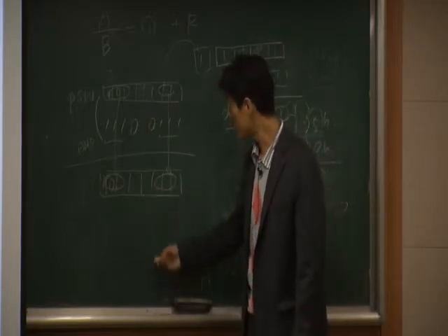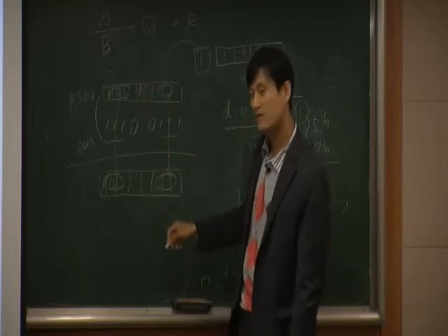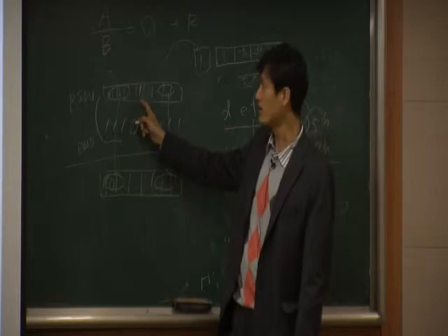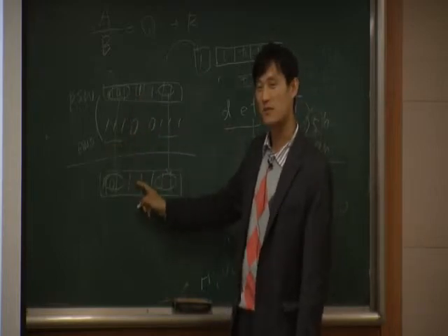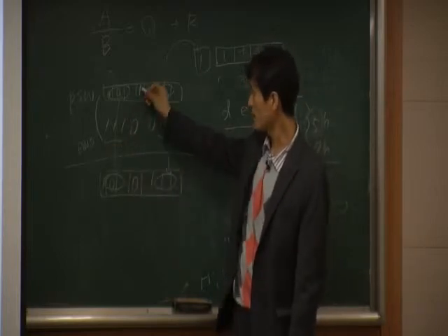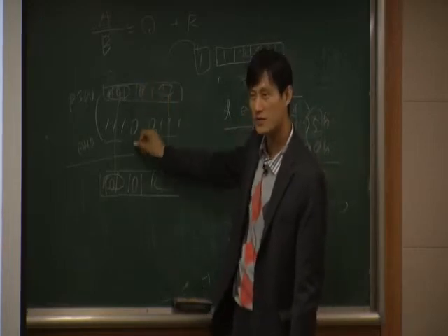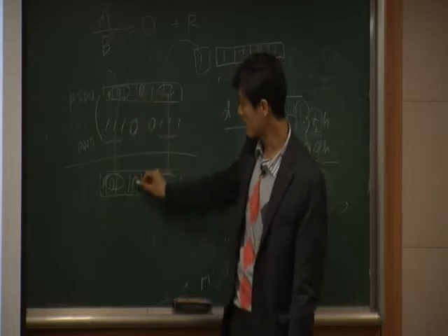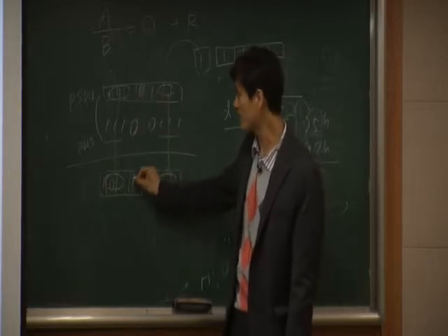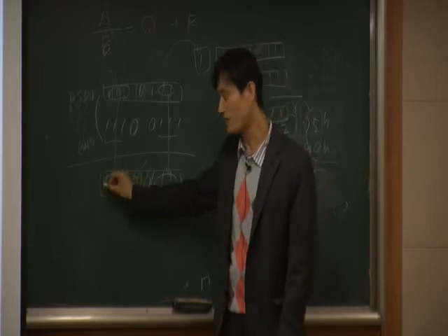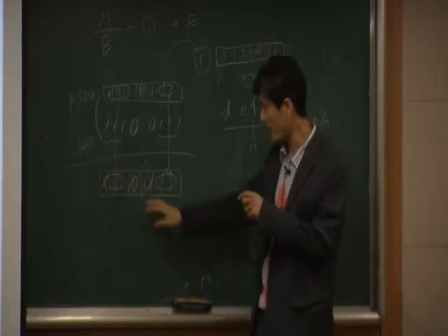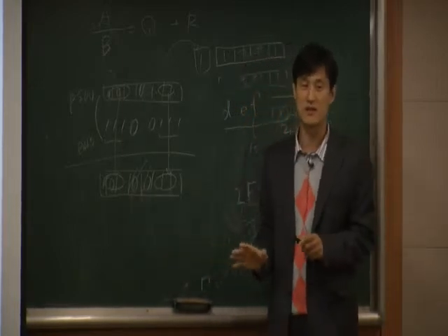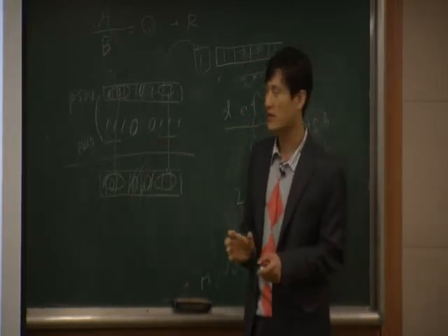Let's say you have the value 1 here in the original PSW. 1 and 0 becomes 0. And let's say you have 0, then 0, 0 anyway is 0. So when you have a 0 and you do AND, then this becomes 0. So you want to clear this. The other values you want to keep the same, but only these 2 values you want to clear. In that case, you use this kind of operation.